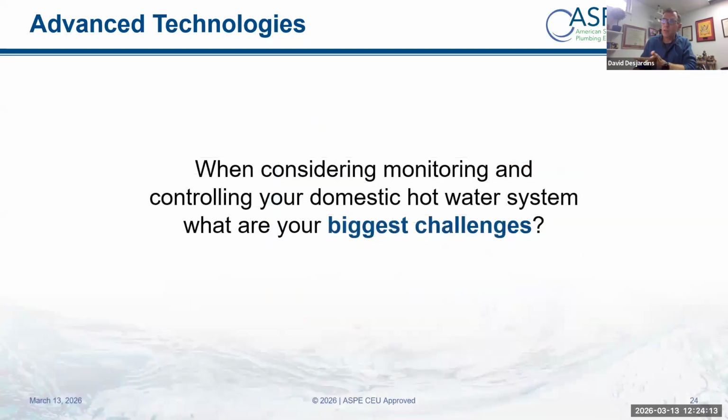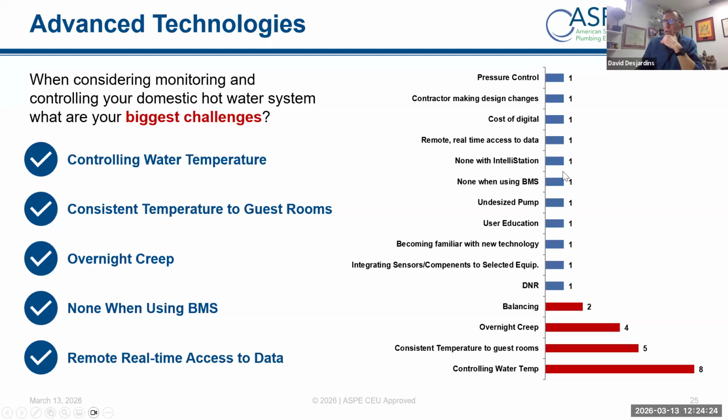If you look at this, some of the challenges we went through, we asked some facilities what they ran into, and you'll see that this gets addressed beautifully with a digital valve. If I look over here, it's basically temperature control, right? Those mechanical valves I looked at, anything over 40 gallons a minute has plus or minus 7 degree temperature control. Depending on where that swing is, that can be very challenging for a facility depending on who they are.